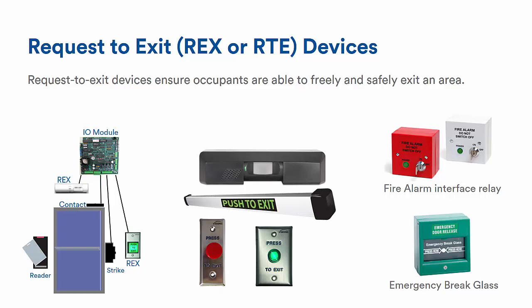Now, a range of interface units are available to connect the fire detection system with other detection equipment or to control plant and fire protection equipment such as conventional detection zones, sprinklers, and fire dampers or door release units. Fire alarm interface relays are meant to cut power to the lock. This cannot be via software due to regulations. It has to be hardwired.